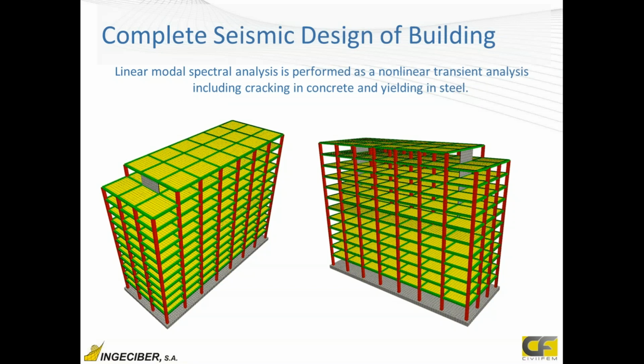We'll see later, and include nonlinearities such as material nonlinearities for the behavior of the concrete, with a multilinear short-term loads stress and strain diagram for these materials. And for steel as well, we can include a bilinear behavior for its stress and strain diagram to take into account yielding or a possible failure of these rebars.